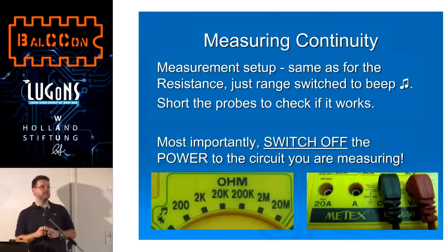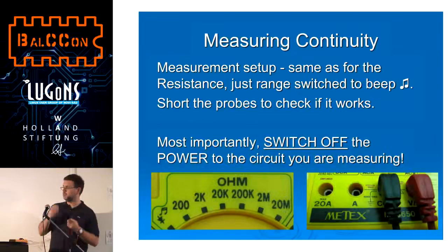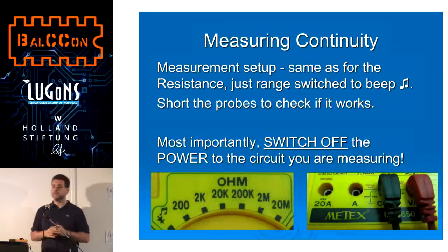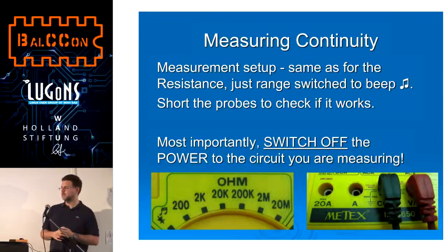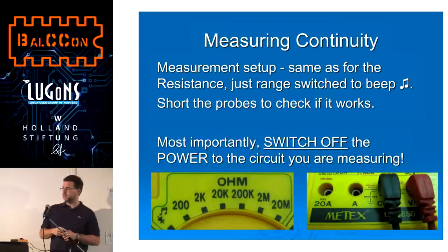One thing is important to remember. Never measure continuity when the device is powered. Always switch off the voltage, because it's the same thing as measuring resistors. You can fry your multimeter if it's powered. So if you're measuring something in your power supply unit, switch it off first.